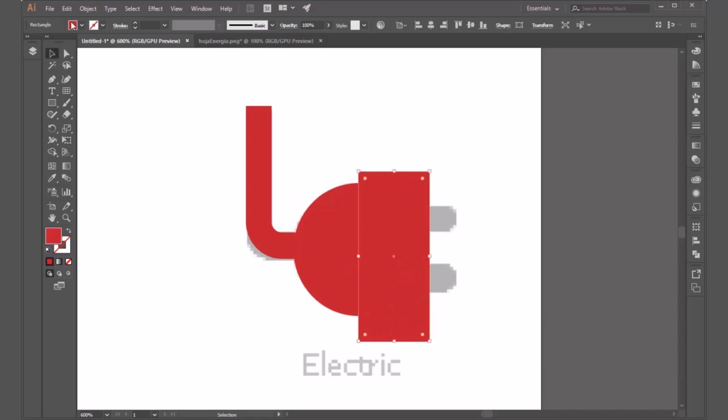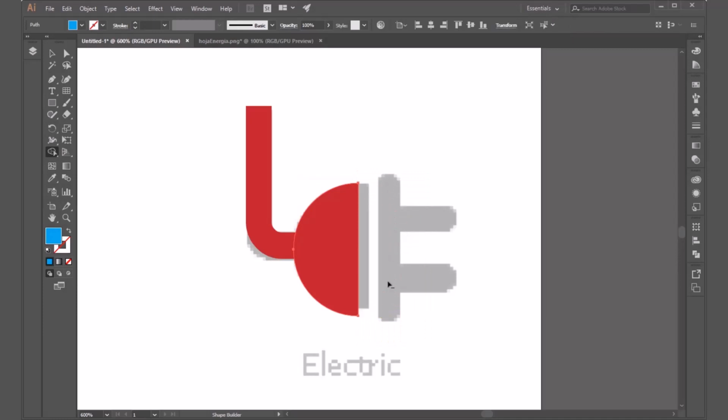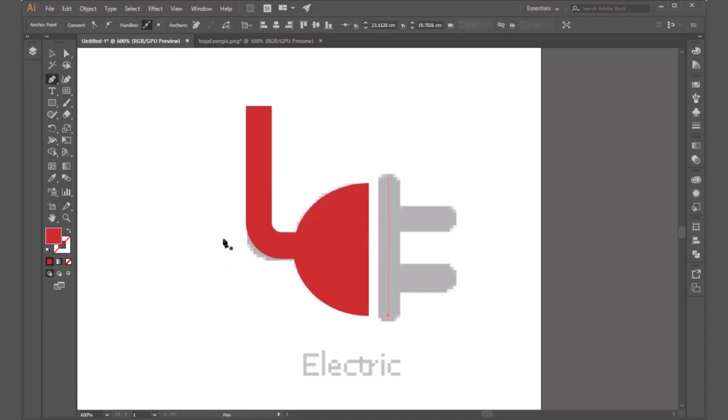All right. Change the color so you can see it better. And now I want to turn this circle into a half circle. You can just select both of them, use the Shape Builder tool, hold Alt, and delete these two areas. Really easy. We created this and just attach these two. And for here, like this, Enter.